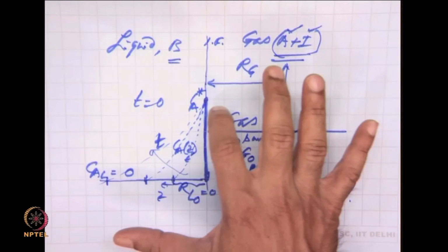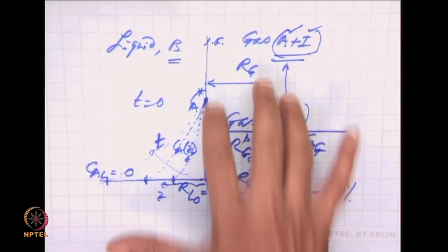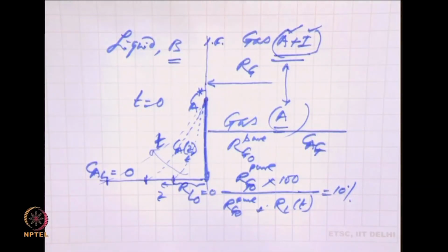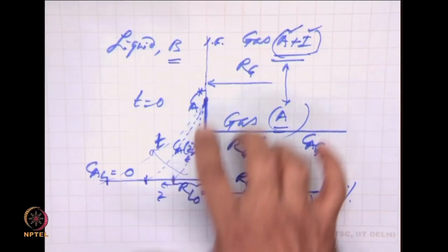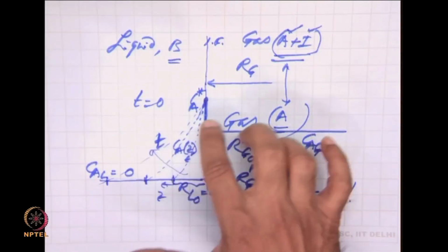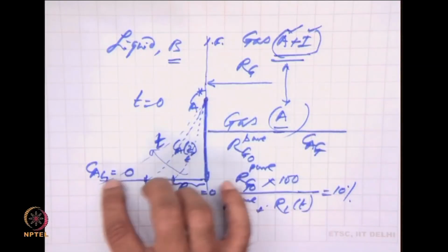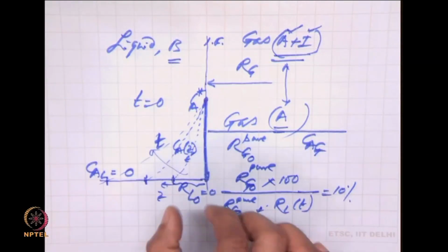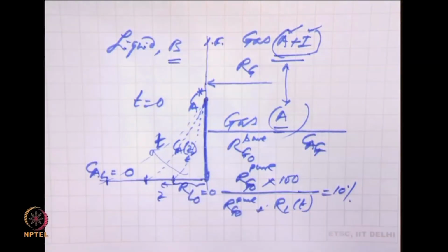Then I argued that as transfer occurs, the concentration at the interface will remain at the saturation concentration, because the gas is pure here, and this gradient now diminishes, becomes finite and lesser as time progresses. That corresponds to the concentration of diffusing A advancing deeper into the liquid. As more and more liquid thickness comes into the picture, the liquid phase resistance increases.